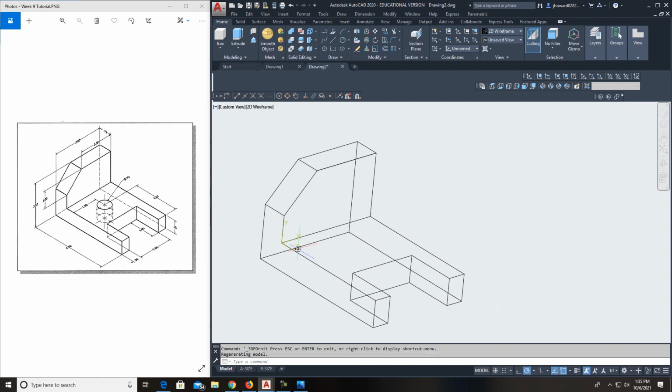Now, let's say for instance, I want to be on this plane up here at the top. Again, hit your 3-point. And I can go from there to there's my X, and back here's my Y. Okay. And put my circle. I can come in here and figure out where my circle goes, and it looks like 1.5 over, offset 1.5, enter there to there.